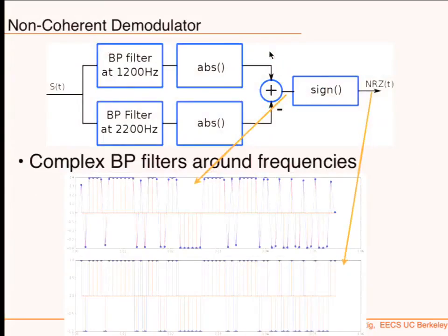Okay, all right, so you're implementing two types of demodulator. One of them is a non-coherent demodulator, where effectively, because it switches between two frequencies, you can put filters around those frequencies. These filters are kind of like a matched filter, right? Because you're sending a pulse over a certain amount of time over a particular frequency. And this is really what you're doing here: your bandpass filter is about the size of a bit, and this is kind of like a matched filter.